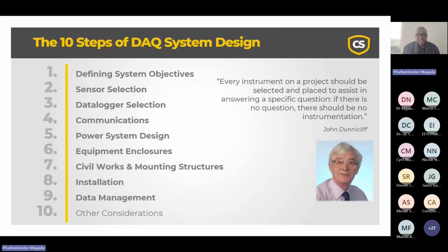There is a quote by John Dunnicliff: "Every instrument on a project should be selected and placed to assist in answering a specific question. If there is no question, there should be no instrumentation." So the first and most important aspect in data acquisition design, we need to define the system objective. We need to identify the specific question the data need to address.